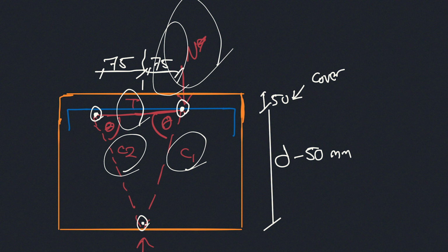What I would like to mention here, because it's really important, is that your tie needs to be extended beyond the node sufficiently to develop the bar in tension. Basically, if your bar is not long enough to be developed beyond the node, it cannot act as a tie. It's just not activated. It will just slide and slip out. So it's important to work out where your node is, which is usually governed by the external loads and by your internal arrangement of the strut and ties.